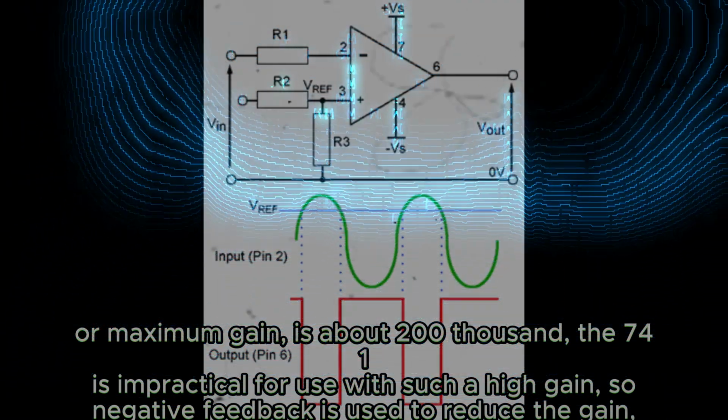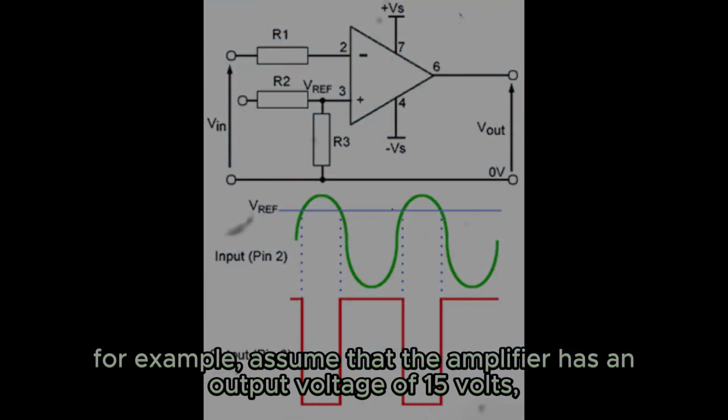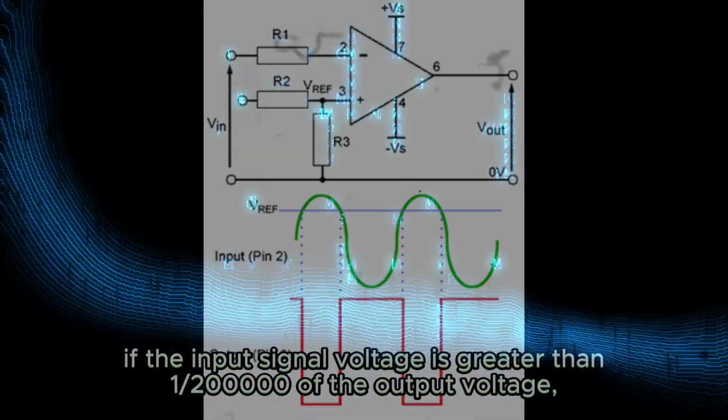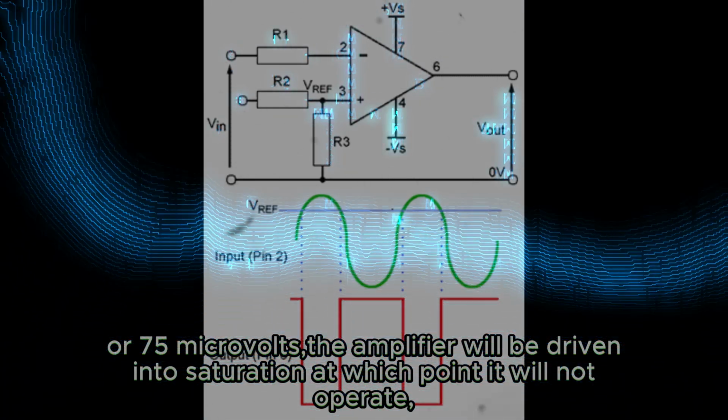For example, assume that the amplifier has an output voltage of 15 volts. If the input signal voltage is greater than 1/200,000th of the output voltage, or 75 microvolts, the amplifier will be driven into saturation, at which point it will not operate.